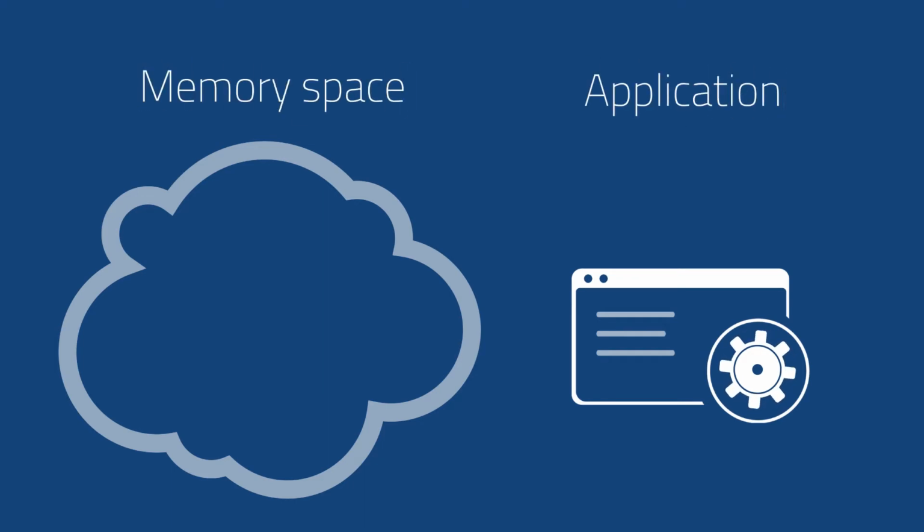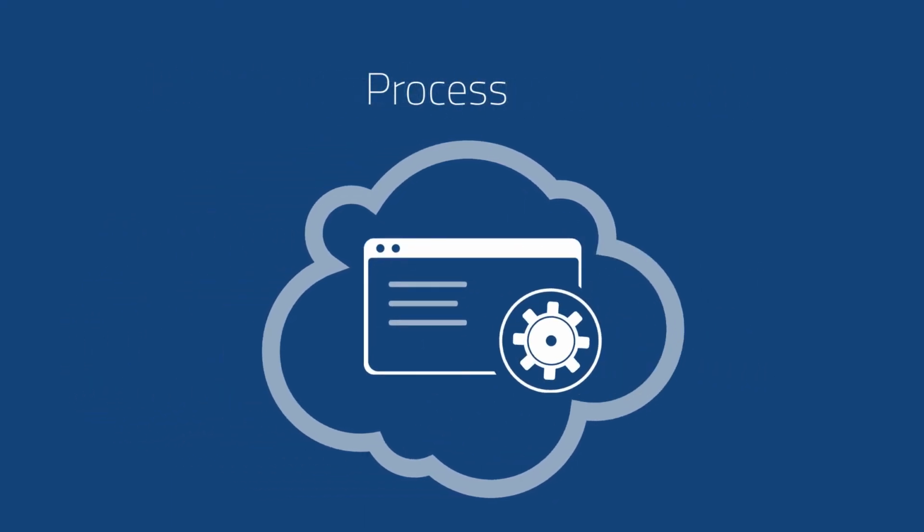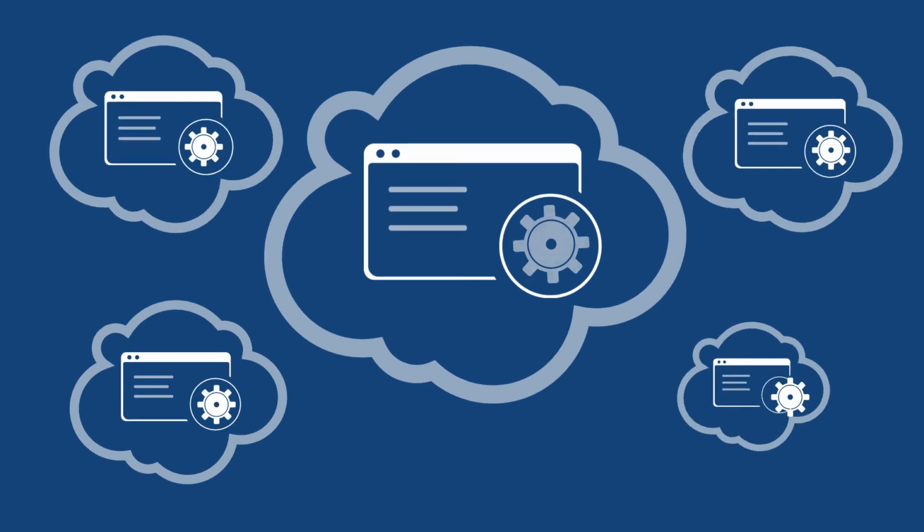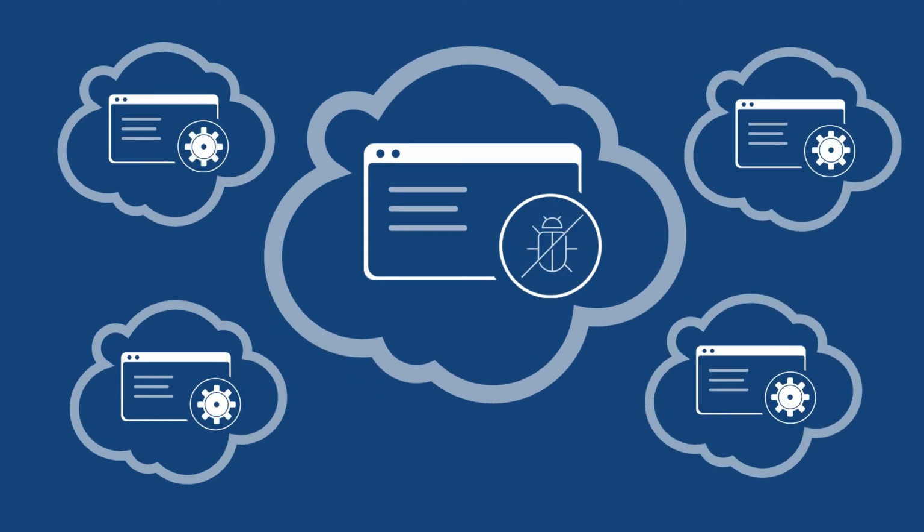So how does this work? On your SoC, you have applications that run inside separate memory spaces. We call that a process, and it gets assigned a unique ID. In winIDEA, you just choose which process you want to debug, and the debug context will switch to it. That's the multi in multi-memory space.